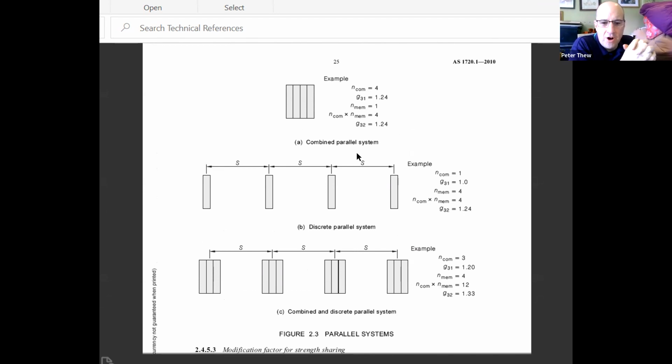So they've already got all the averaging you can imagine. Next time you're in the structures lab, there's a piece of LVL in there. I'll show it to you, and it's about 20 laminates all glued together. So you think of it like this, it's 20 beams stuck together. And so because we've already got 20 of them stuck together, they've already built K9 into the member, I guess, would be the way of saying it.